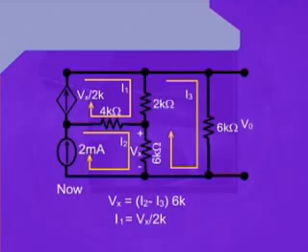Now, why we have taken I2 minus I3? Once again, the reason is the same as we have been discussing in the previous lectures, that the current I2 through this resistance, which is having a value of 6 kilo ohm, is passing in the clockwise direction, whereas the current I3, which belongs to the mesh number 3, flows through this resistance into the opposite direction as compared to I2.